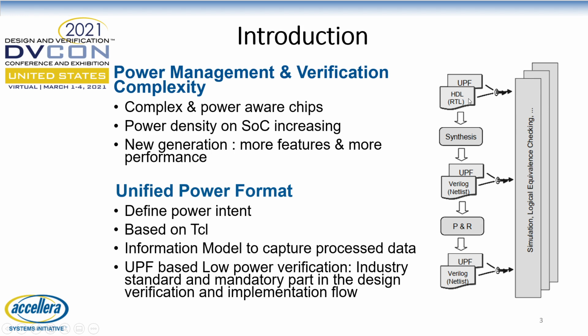UPF provides a consistent format to specify power design information that may not be easily specifiable in an HDL. As indicated in the figure, UPF files are part of the design source and when combined with HDL represent a complete design description, HDL describing the logical intent and UPF describing the power intent. This collection of source files is the input to several tools, for example, simulation tools, synthesis tools, formal verification tools.